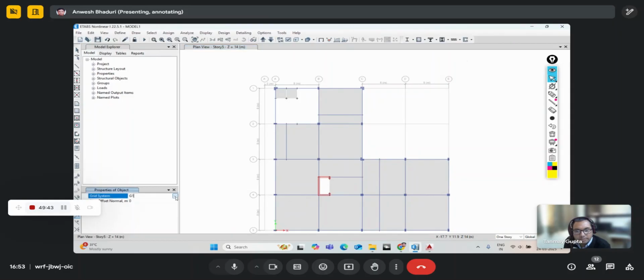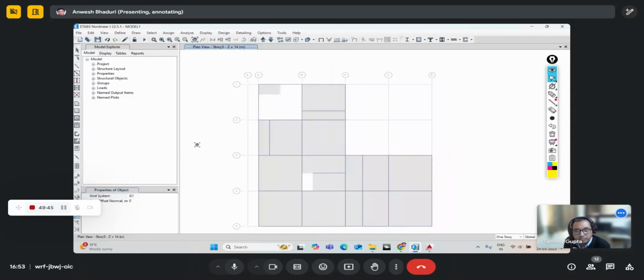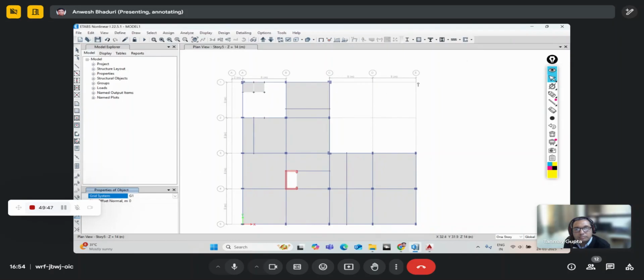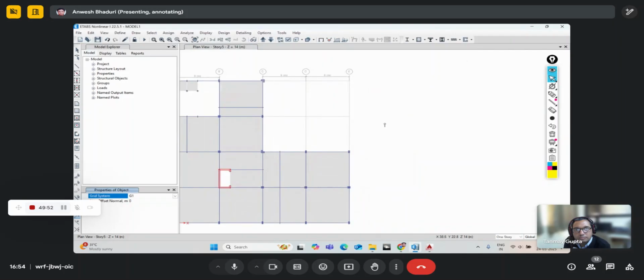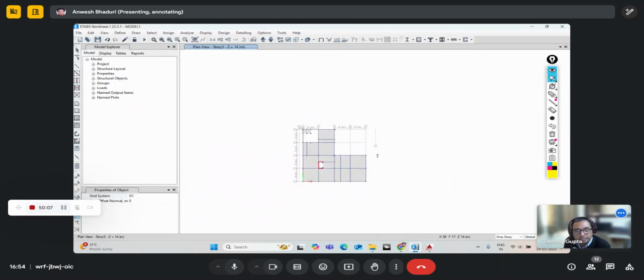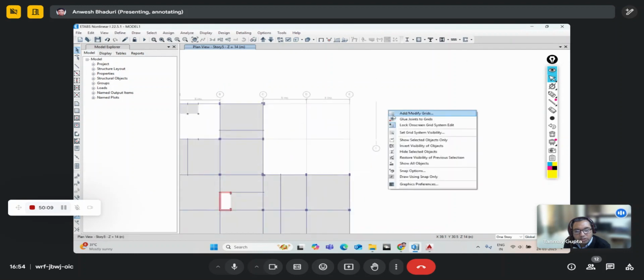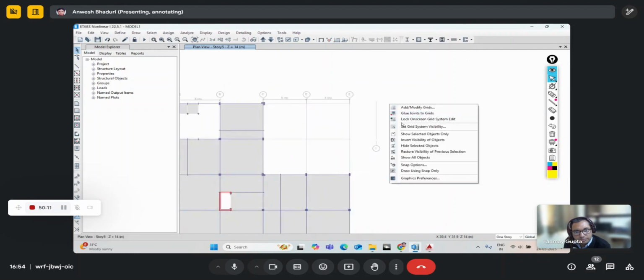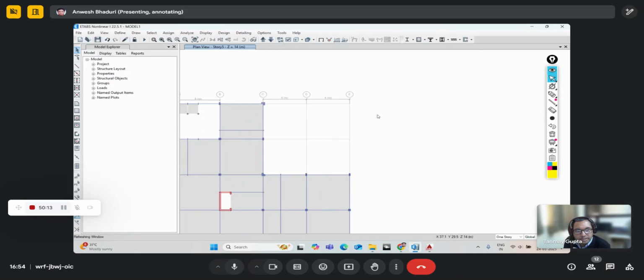I have just one grid system now, so I'll draw this grid in G1 itself. Say you had drawn some structure over here, and you want to just draw the grids. So say you have a joint here, you have another joint here. So you do that, you see your grid will come up. This is part of G1.